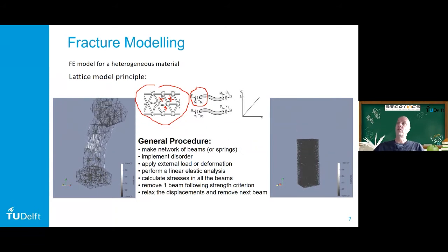And in the simulations, you load this network with a force or a displacement, and it's just a linear elastic analysis. So just linear elastic, you solve all the forces in the network, you take out one element, and you do again a linear elastic analysis. So it's a sequential linear elastic analysis. So you always find a solution, and it's quite fast. Even for large networks, you can propagate a crack within minutes, hours, or days, depending on the computer that you have and how big you make your system.